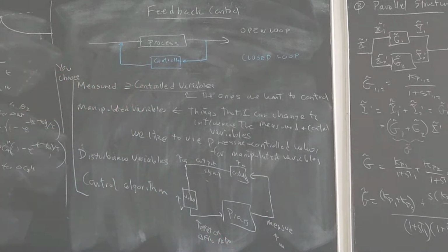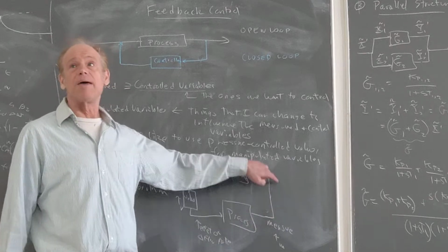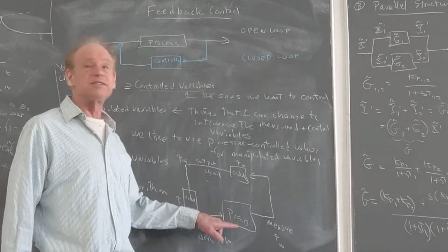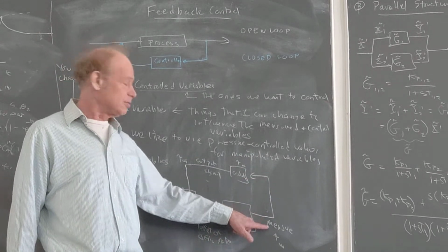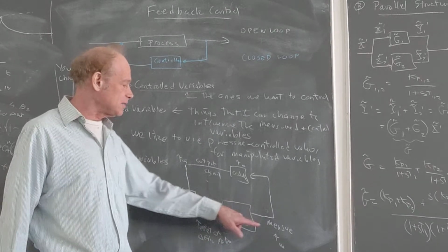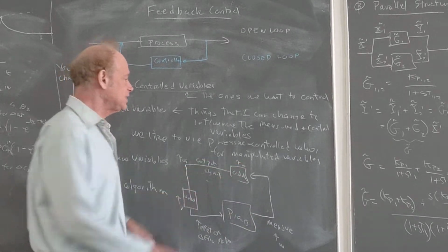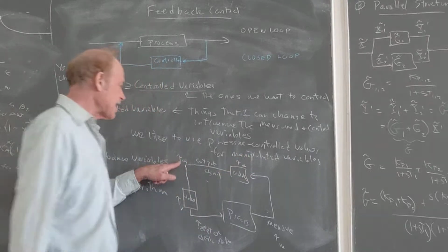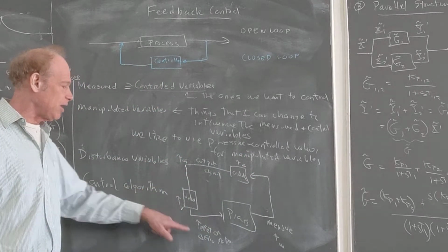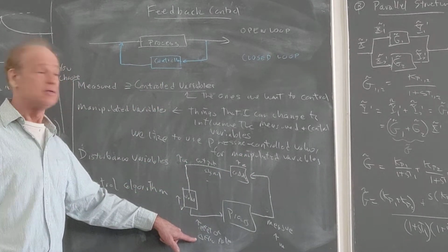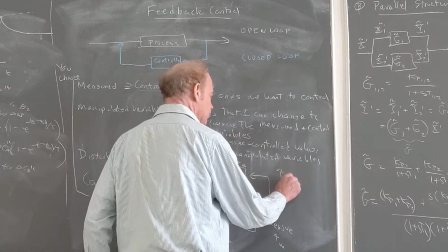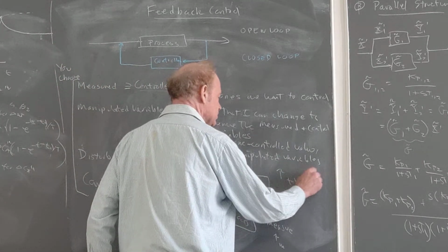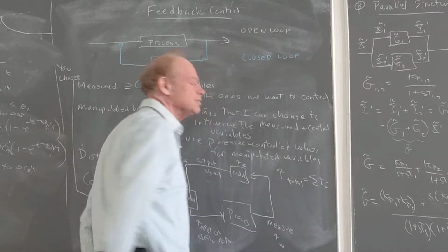So when I measure something, and I have all these time scales, it's the total time that contributes. That is, I measure something that goes wrong. Until I see an effect, I see tau m plus tau c plus tau output signal plus tau v plus tau effect. So the tau total is equal to the sum of all the tau i's.